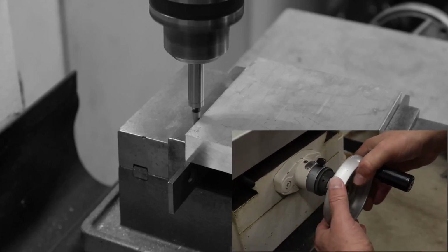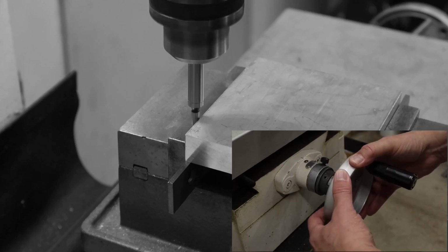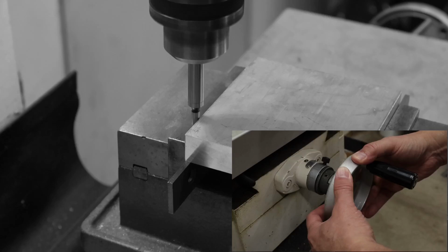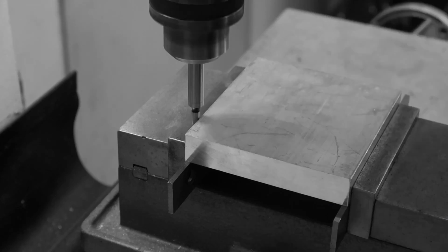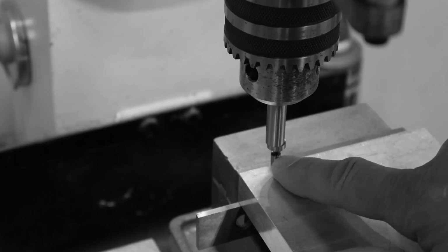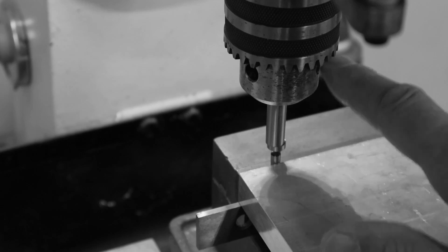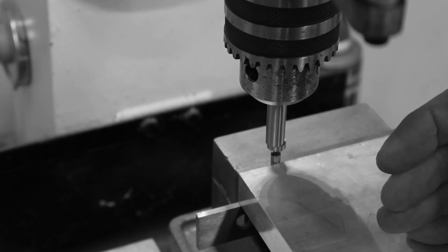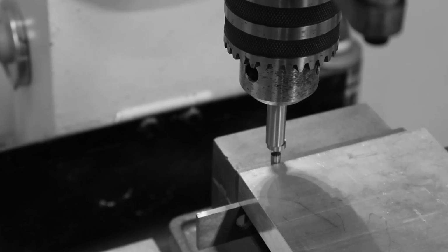Now I'm going to start going really, really slow on the dial until you'll see it shift to the side, the very tip, this lower portion. Once I'm perfectly in contact, it will shift one way or the other. Now you can see how the tip of the edge finder shifted over. That's perfect. We came into perfect touch. You need to stop as soon as it does that. You don't want to keep feeding in to go too far.